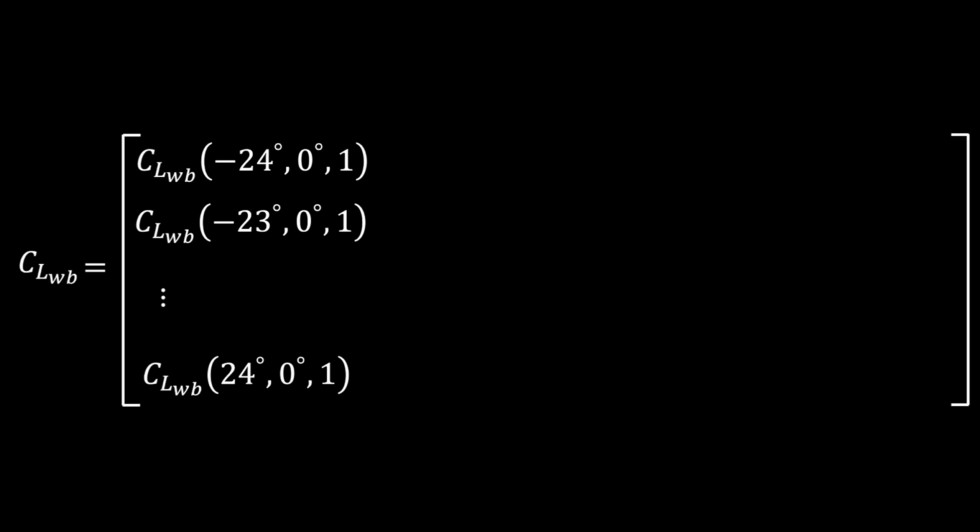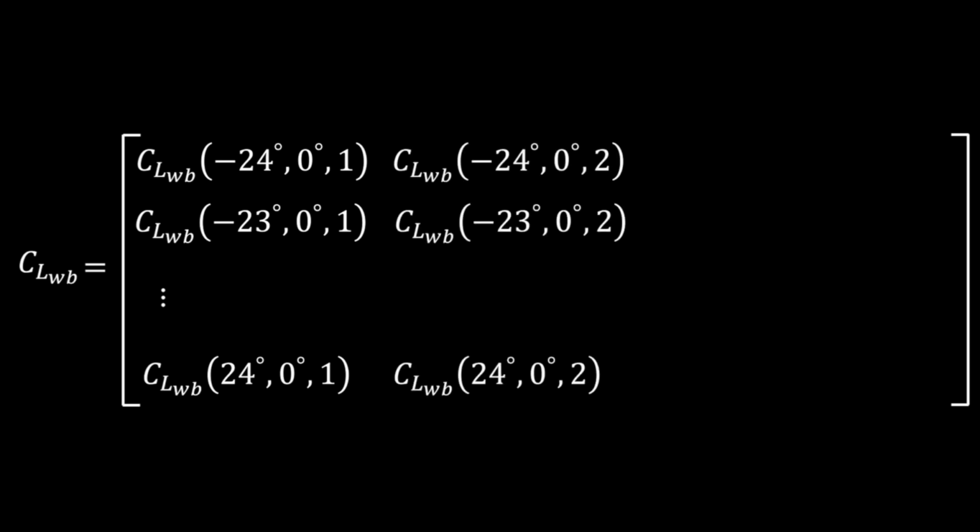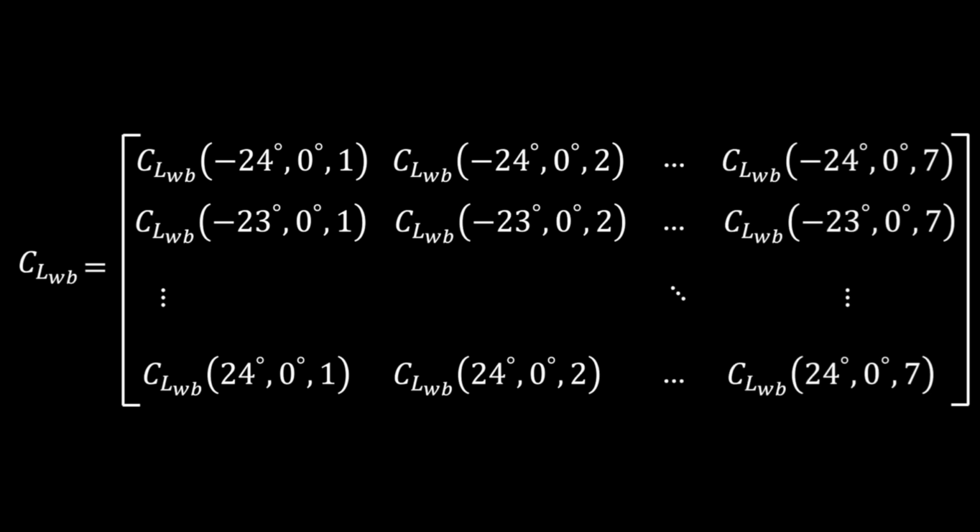And that process would be repeated for the next desired Mach number, and so on, until all data at all desired Mach numbers and angles of attack are obtained. In doing so, we create a table of lift coefficient data.